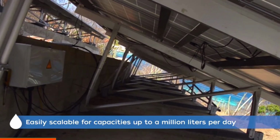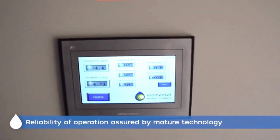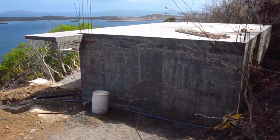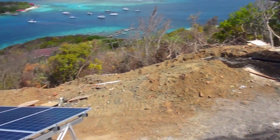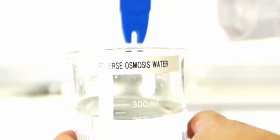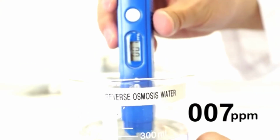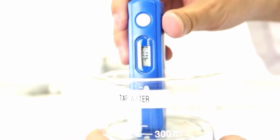The best advantages are that they have a great capacity, a reliability of operation assured by mature technology, and of course, fossil fuels are totally avoided. One disadvantage is that the performance of reverse osmosis systems decreases significantly with unwanted particles on membrane surfaces, which is typically defined as fouling or scaling. This is due to the dissolved organic and inorganic salts in the intake water, which cannot be totally eliminated. One way to make sure it's all good is measuring it.